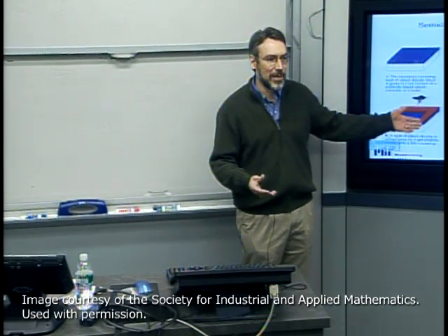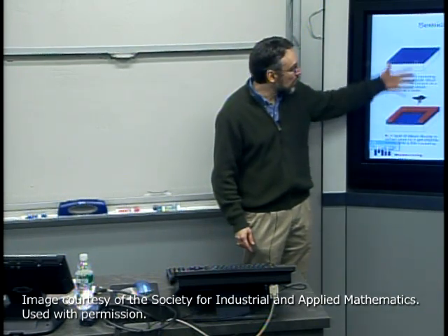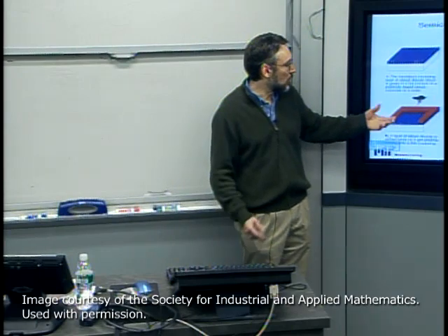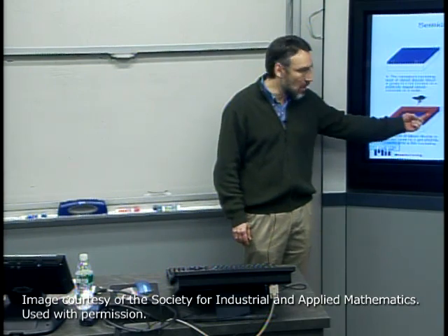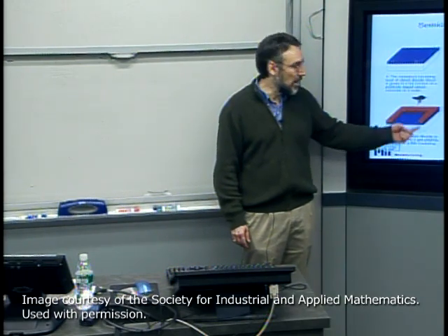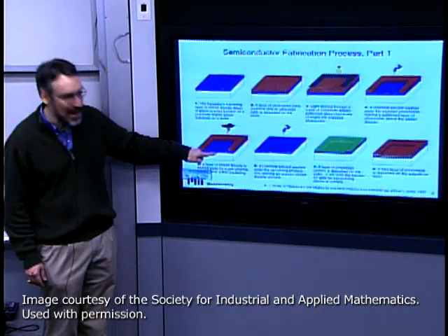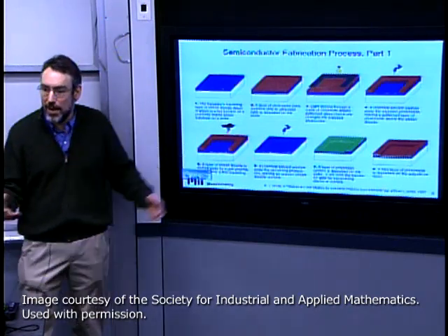So what do you think they really do? Etch all the way through, then grow another layer? That's exactly right. We can controllably etch all the way through using ideas of etch selectivity. The same idea I mentioned of we can choose an etch chemistry that allows us to etch silicon dioxide and not etch photoresist. We can also use one to etch silicon dioxide but not etch silicon. You can have very good selectivity so that one can stop controllably on the surface of the silicon.